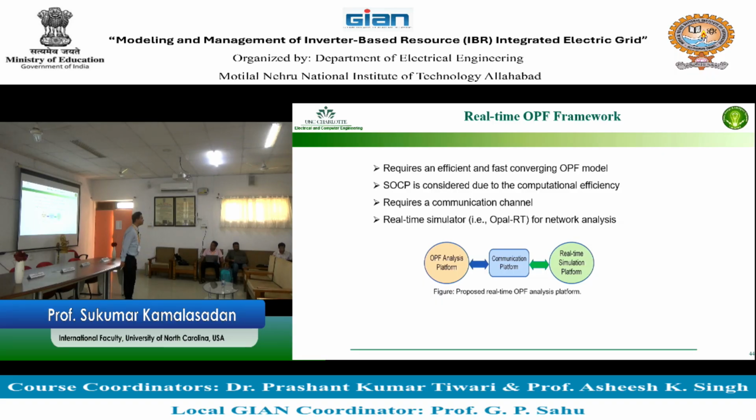Can you send the voltages to the distribution network, saying this is the voltage I get if you have the power at this point? If you want to change the reactive power, then my voltage may be improved. So can you send that as an actual voltage for a specific point? Because actual voltage at a point you cannot measure, right? Because you need to have somebody to do that too. So these are the inputs that go to the field from the power flow or optimal power flow.